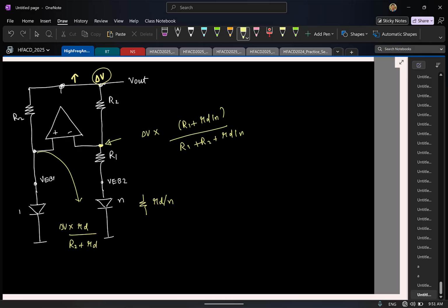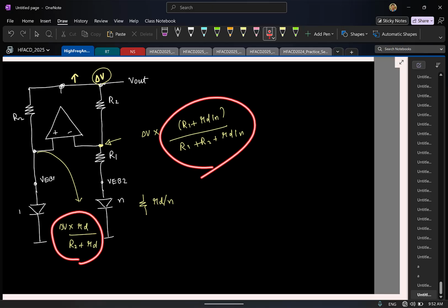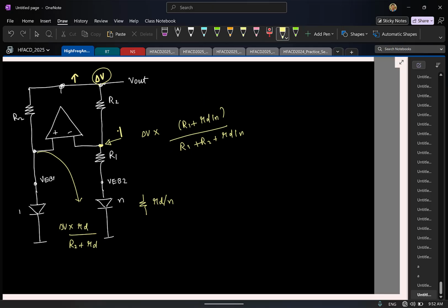Okay. So which of the two is higher now, left side or right side? The diode resistance, is it small or very large? It's going to be really small. So then tell me if the left side is higher or right side is higher? Right side is higher. So this will increase more than the left side. Assume that the diode is even a short, for simplicity. So then do you think we have strong negative feedback or positive feedback now?